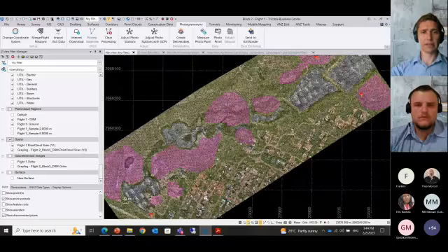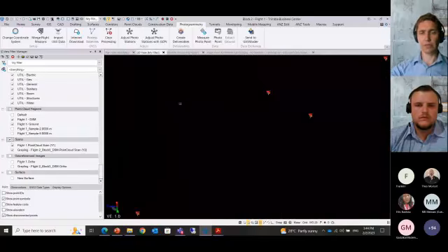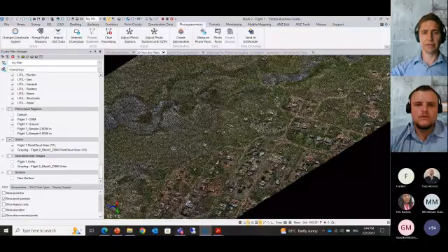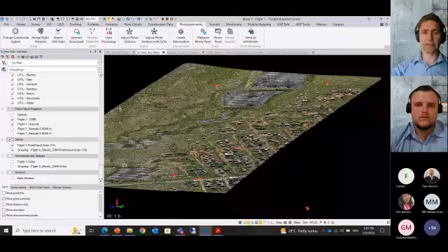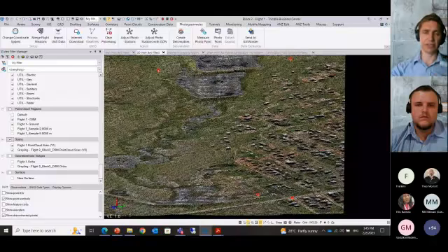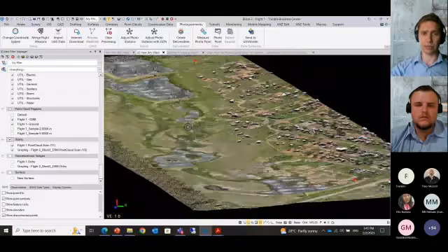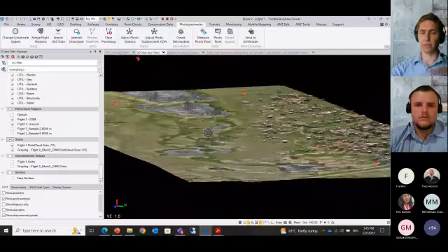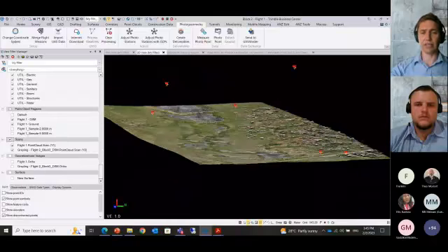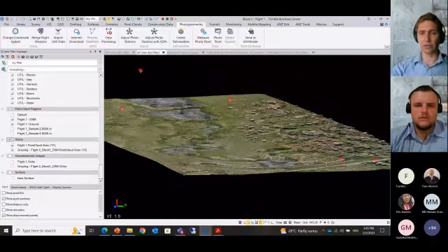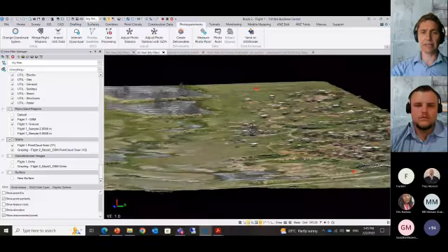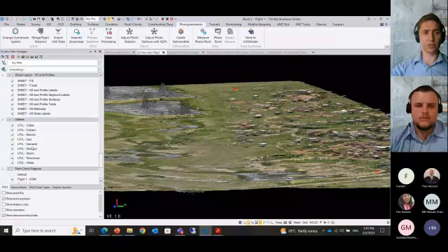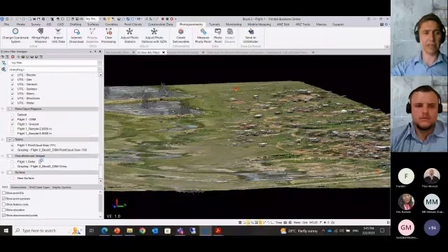Okay, so that's that. If I go over to my 3D view, you'll see my CAD, okay, there we go. For those magenta areas, I didn't drape the CAD to the point cloud. I just did an elevation for that. That's why the CAD is not actually on the point cloud, but that is now the point cloud data set. So what you can now do is also the classification part.